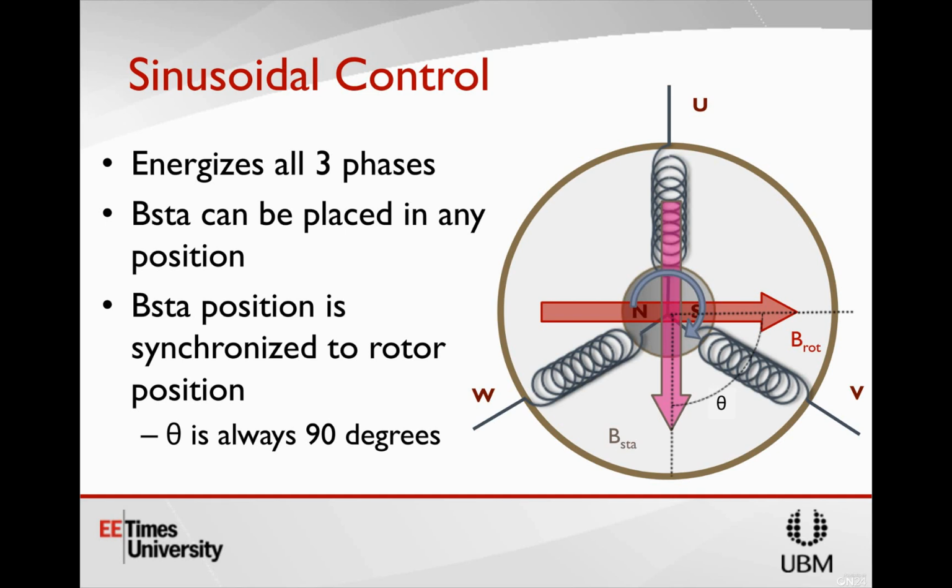Now you can also do a lot of other things. You can even integrate Hall sensors into sensorless for your startup considerations. By using the Hall sensor, you can get an initial guess as to where the motor is. And then from there, you can choose that as your seed angle.